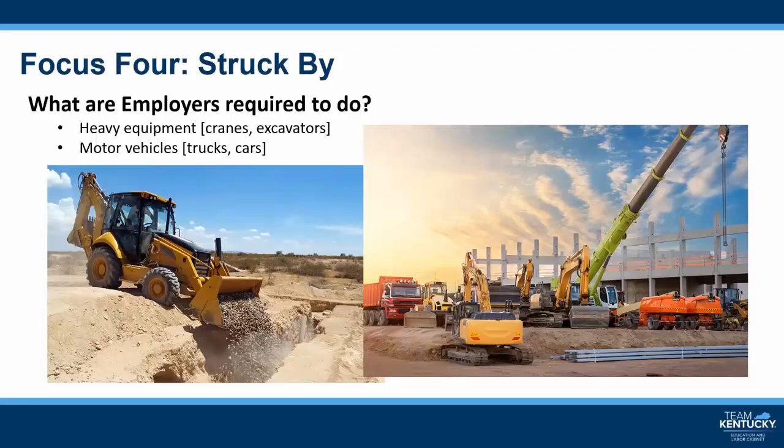They also need to assess the hazards within the work zone that would affect the safe operation of hoisting equipment, such as power lines and objects or personnel that would be within the swing radius of the hoisting equipment. Employers need to erect barriers to mark the area covered by rotating superstructure to warn workers of the danger zone. They also need to ensure that the equipment is in safe operating condition via the required inspections.